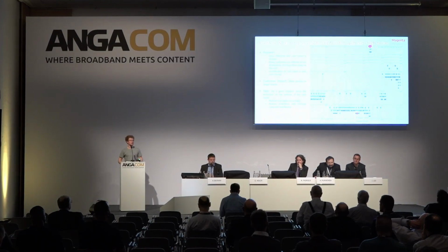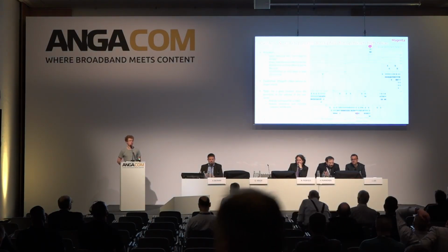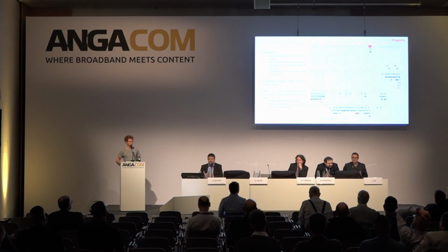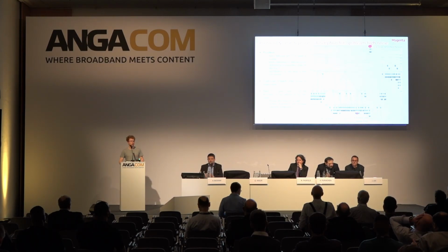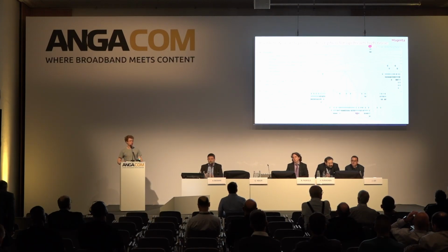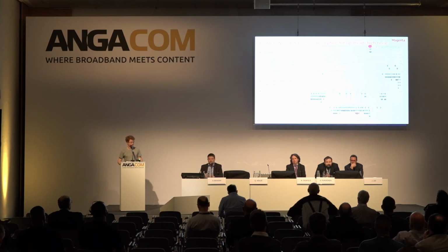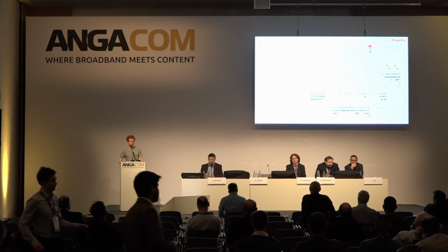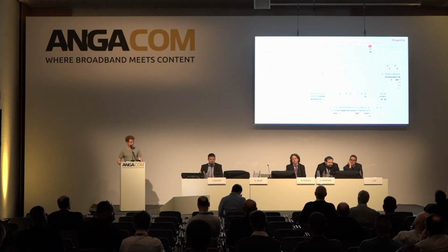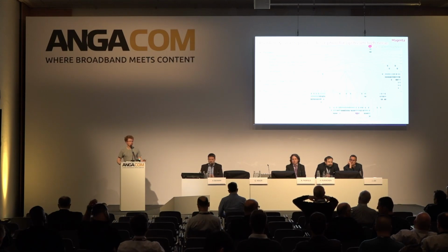So I want to talk about high noise issues in the network. I think most of the people at this conference might be familiar with the problem. We have issues that are detected at the root of the topology of the network. The CMTS will show that we have a problem somewhere in that specific fiber node area, but we will not be able to exactly pinpoint one specific device as the root cause. As the problem propagates up towards the fiber node from one device, more and more can be affected. In fact, the customer impact can be fairly severe, such as no service being available in that specific network